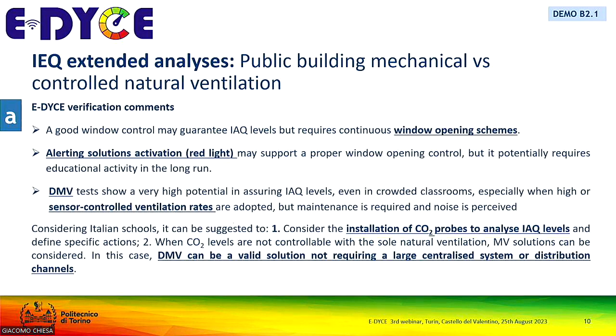Now we install 3 mechanical ventilation units, remotely controllable, and we test 7 or 8 control solutions, like time-based, something more connected to double threshold or single threshold, and variation of the threshold itself. And we see that with that we can also control the more critical rooms, like for example the smaller rooms with a lot of children. So even when opening the window, in some cases we may have problems in terms of CO2. But it's also interesting to see the post-COVID evaluation, when we have a master of the school that requires a specific control logic in the manual operation, so each 2 hours you need to open and so on, the CO2 may be controlled.